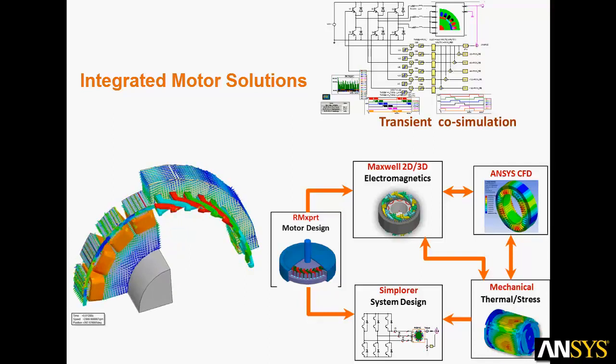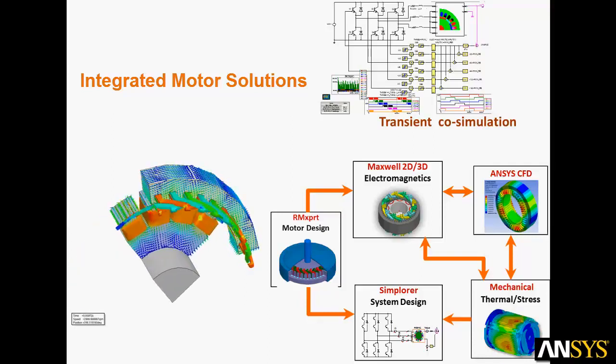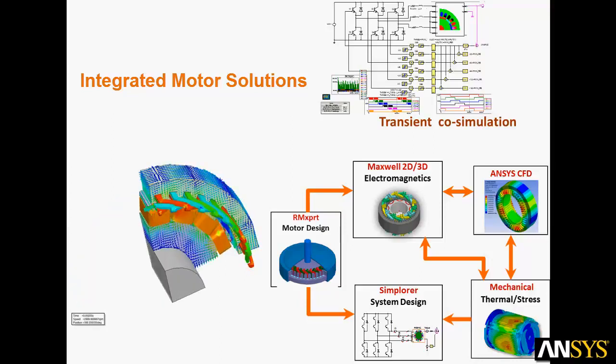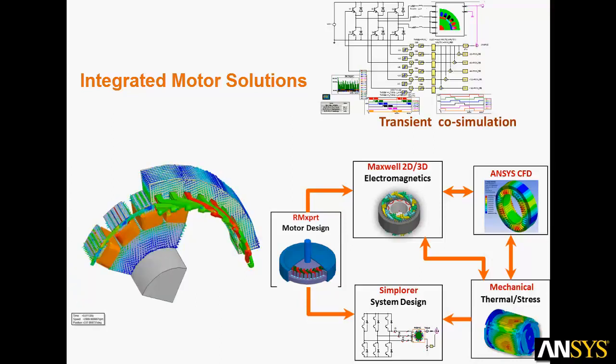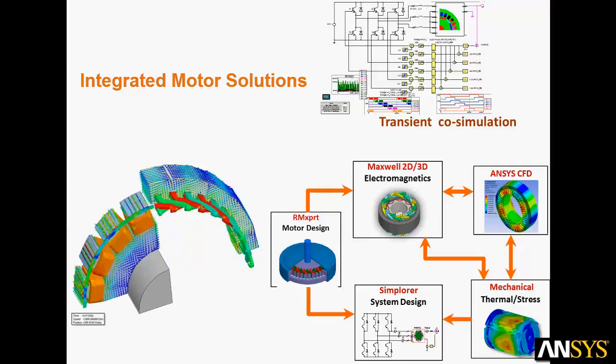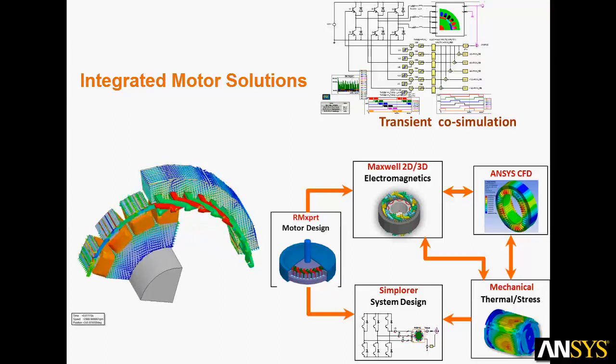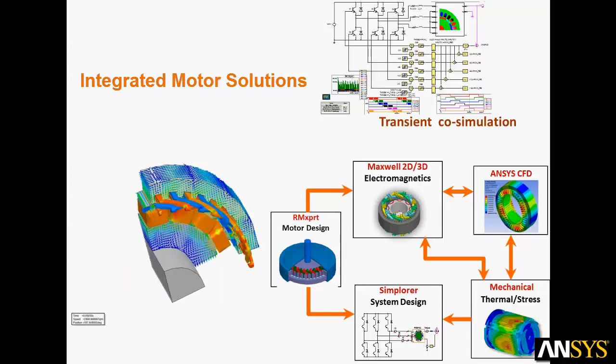RMExpert provides the initial motor design and 2D and 3D models. Maxwell performs 2D and 3D electromagnetics analysis. Ansys CFD and Ansys Mechanical are used for thermal and mechanical stress, and Simplorer ties all the physics together in a top-level system for drive circuits and other behavioral components.